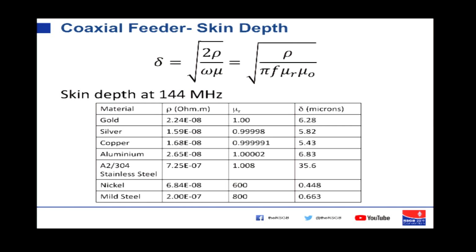Right, so practical things. Calculate the numbers. Here are some materials, and here are their skin depths. So these are things that are worth remembering. This is worked out at 2 gigahertz. So at 2 gigahertz in gold, the skin depth is just 6 microns, 6 millionths of a meter. All the current has to go through that layer, essentially. Now your resistances are going up and your losses are going up. Silver's a little better. Copper's better still, but doesn't tend to do too well when it tarnishes. Aluminium's pretty good too. Obviously, if that oxidizes, you won't get any current flowing through, for example, a connector. Believe it or not, there are coax connectors made out of aluminium. Some very interesting wartime products, Second World War products of that nature.